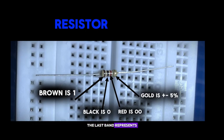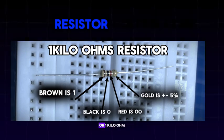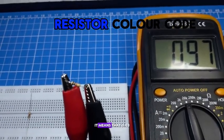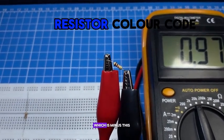The last band represents the tolerance level, and the tolerance level of the resistor is plus or minus 5% tolerance. So in this case, the resistance value of this resistor is 1000 ohms with plus or minus 5%, or 1 kilo ohm. As you can see on the multimeter, it is showing 0.97 kilo ohms. It means that 0.03 kilo ohms is the 5% tolerance, which is minus.